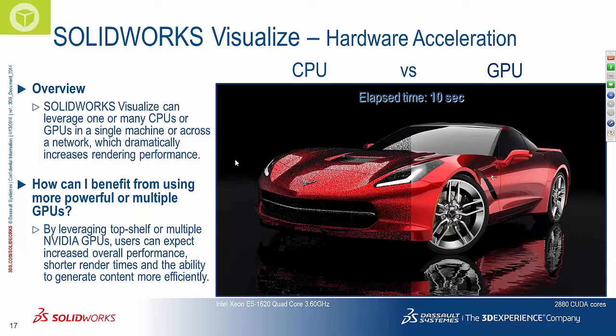If you're running a really high-end graphics card, the hybrid mode can slow you down a little bit, so I just recommend, if you're using an M5100 or any of the K6000, 7000, 8000 series, just run it strictly in GPU mode. So that's my spiel on GPUs. If you guys have any more questions about that, go ahead and type them in the chat and we'll talk about it towards the end.